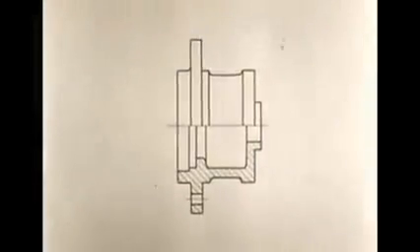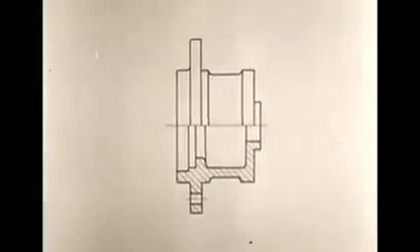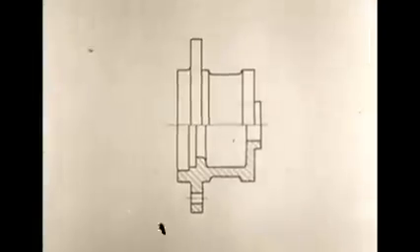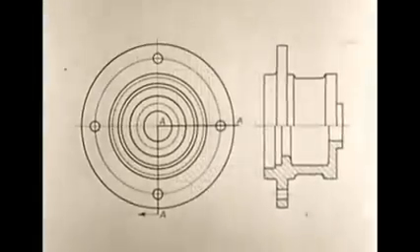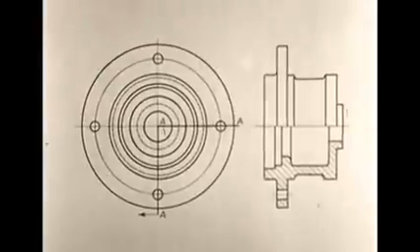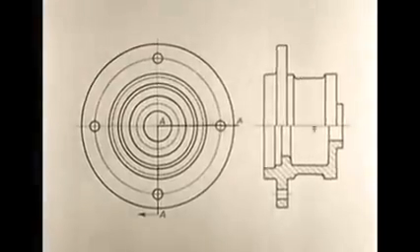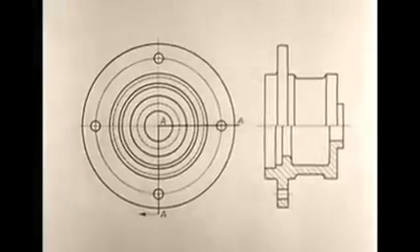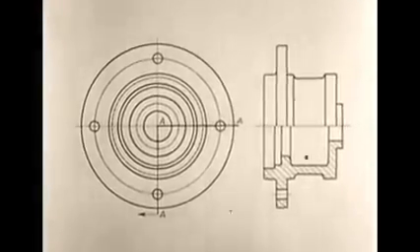When you draw a half section, use a center line through the view, but not an edge line. No edge should be shown because the cut is imaginary and the object is actually not cut. Show the cutting plane line, arrows, and reference letters. Use a half section whenever it will show the details of the object more clearly than a full section will do.